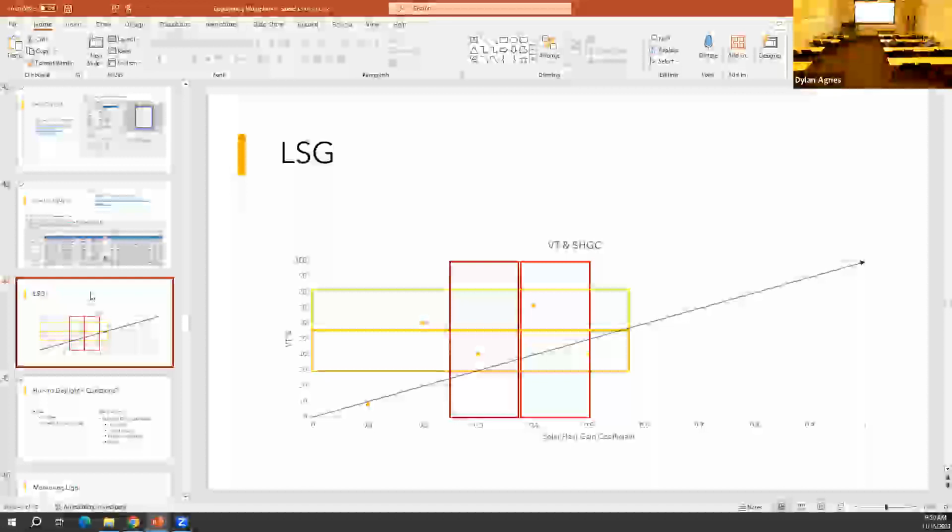But depending on, orientation is another big one that will impact energy performance, as well as daylighting. And as much as I love daylighting, you should do it based off of energy performance and then daylighting, just for overall quality of building performance. Daylighting is a very statistical range method of design. You're always operating in a range. It's very hard to pinpoint and narrow something down, unfortunately. So look at the energy part of it first.